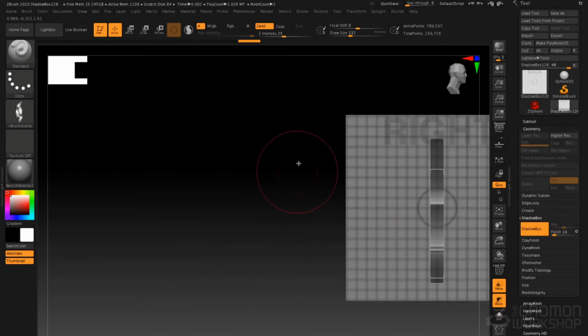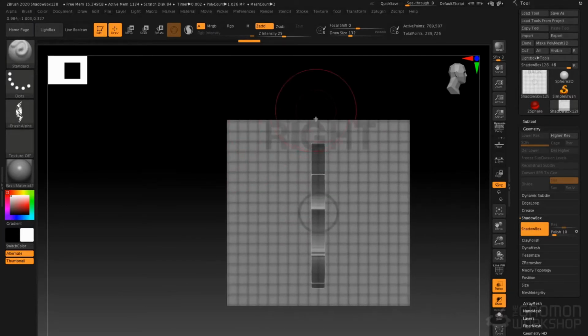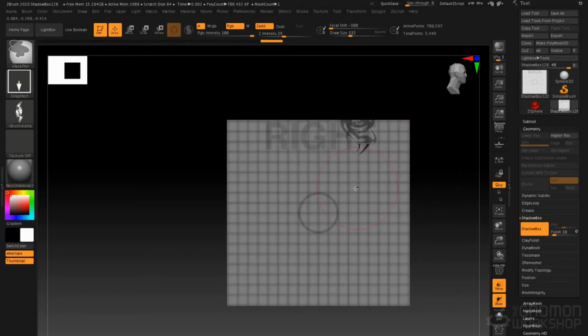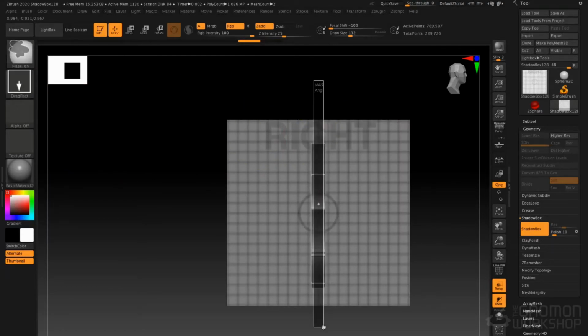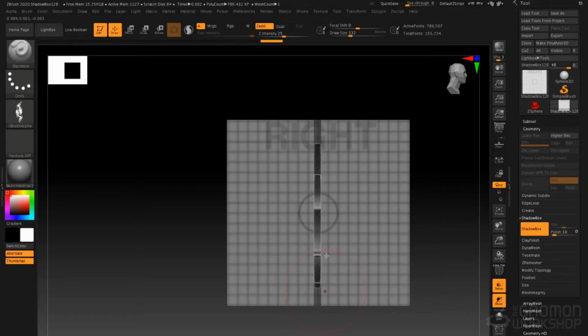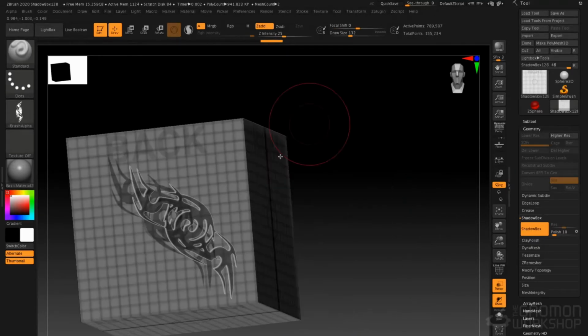Now I'm going to go to the right view, the side view, and I want to limit its thickness. So I'm going to draw a mask marquee right here. I do not want that alpha as part of it, so I'm going to undo that mask, make sure that I turn off the alpha, Control, click and drag to give myself that rectangular masking marquee, and then that limits the thickness of that item.